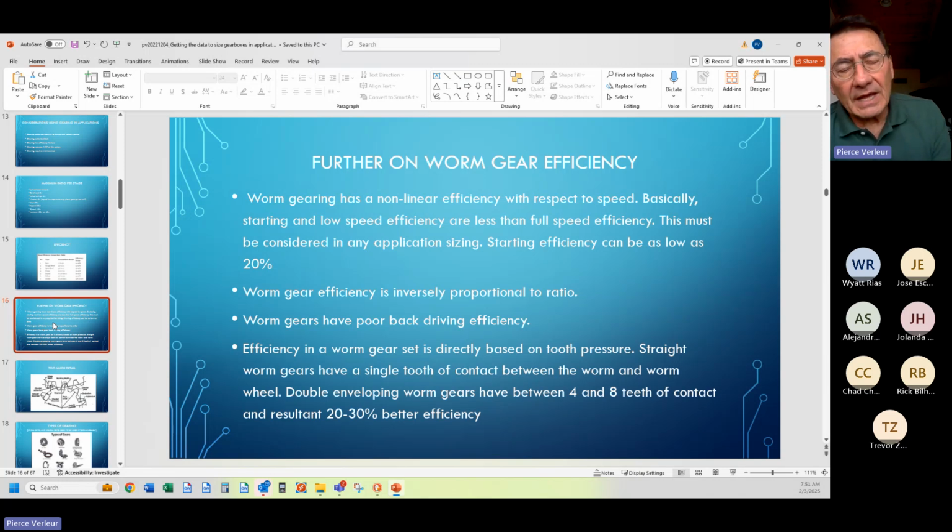When we go over the top of that hill and start going down the other side of the hill, the load is now pushing torque back against the gearbox. The motor is in negative torque or regeneration mode, resisting the free fall of the load while still controlling the velocity. When the load pushes back against normal gearing, the ratios are the same. So if you go over the top of that hill with a helical or a planetary gear set, the motor's going to do all the work to resist the load accelerating to free fall.